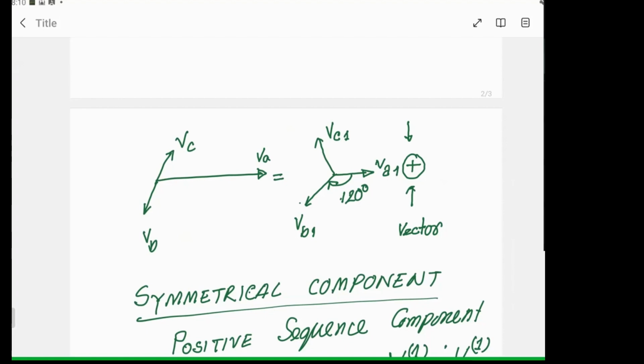It tells everything: this voltage is 20 and all the time it remains 20. But for AC, you have to mention three characteristics to give a proper description. And what are these three? Magnitude, that means peak value, then frequency and the phase angle. If you change any of these three, that signal will be different from the other.